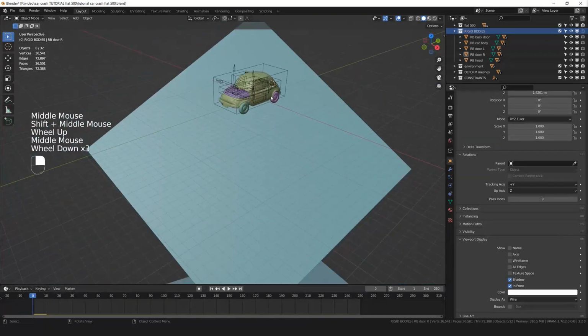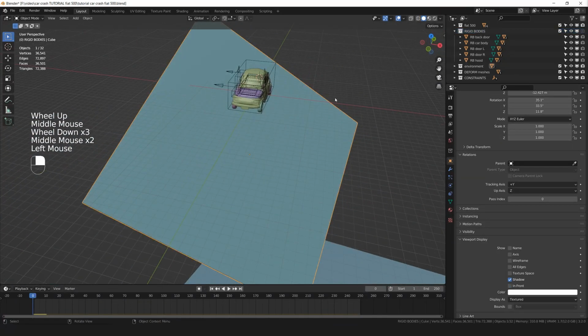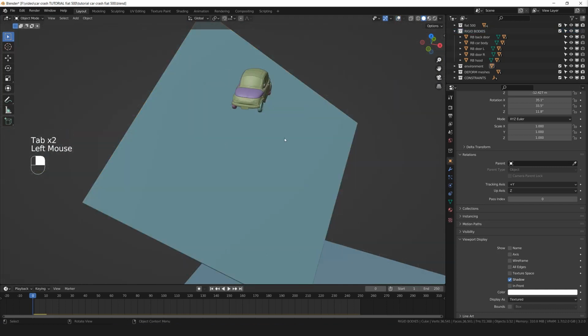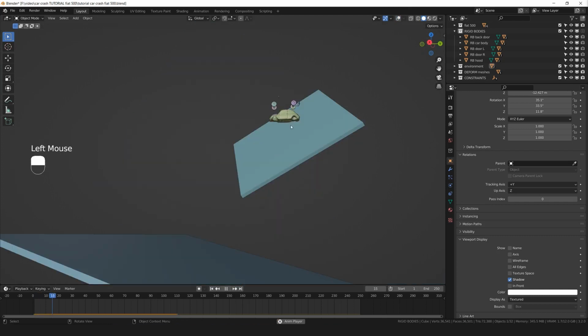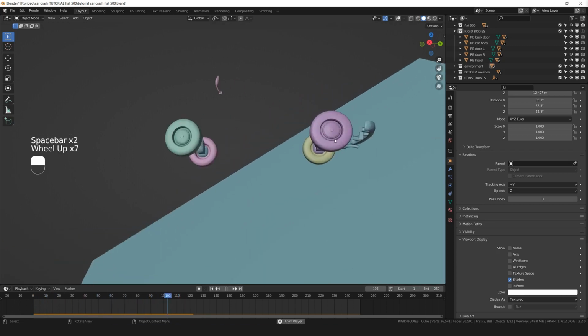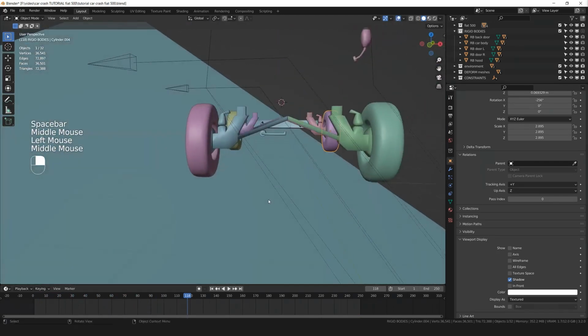So I want to see how it's looking right now in the animation, but before playing the animation, as I said, I select this, press Tab again, and now we can finally properly play the animation and see what's going on. As you can see, everything is playing correctly, correct rotations, and so we are done with the deformable parts. And now it's time to think about all these objects that will not be deformable. And that's why it's gonna be much easier.